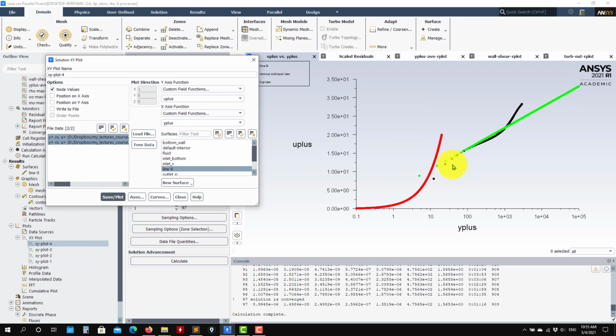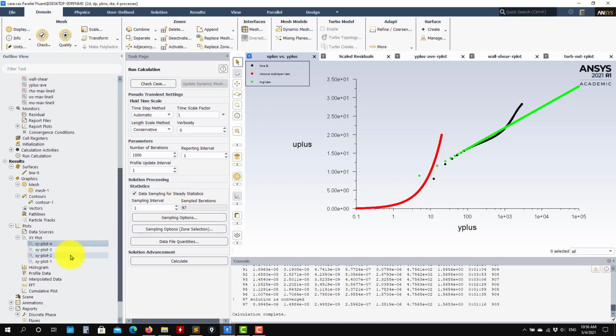So see here that we have a relatively good agreement. We have a rather narrow overlap region, and then we have the defect region where they separate. So in this case, for instance, if you want to resolve the viscous layer, this is just telling you that you need to have a finer mesh. So it's up to you, you can redo this solution. But what is interesting is that we see something similar to what the theory says.